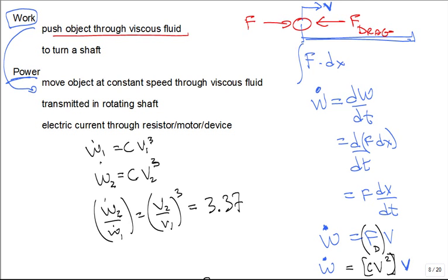All right. Now let's go to rotating or turning a shaft. If I have a shaft, shafts are often used to transmit torque. Let's put this symbol, tau, for torque. That's our torque, okay? And then you can rotate a shaft through an angle of rotation, theta. We'll let the angle theta be in what type of units would theta be in? Radians. See how much you've learned?